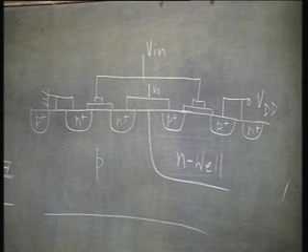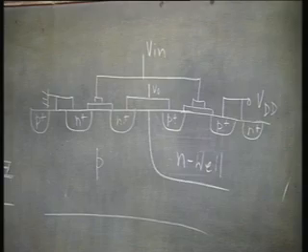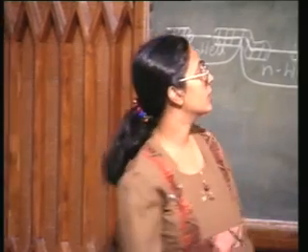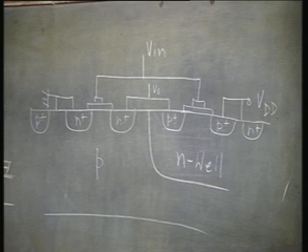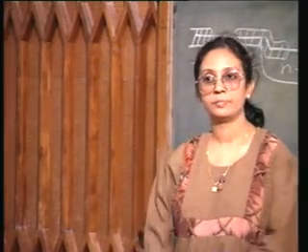The process just goes on and on. It becomes a regenerative process. So, even if this noise signal is momentary and even if it is withdrawn afterwards, it does not stop, the process just continues. So, this is called the latch-up.